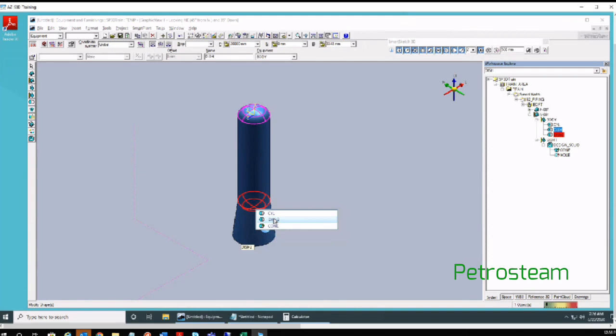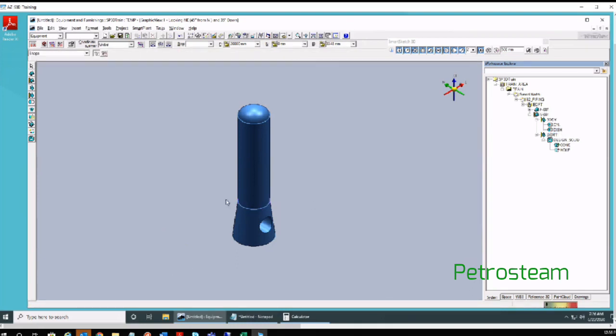Now my requirement is keeping the locate drop down on shape. I will come back to your question, where you asked what if we missed some sequence. What if I have not placed this dish 2? Say there is no dish 2 available. Then also you can select the body. Right now with shape active, you are not able to select any equipment or equipment component. You can select only shapes.